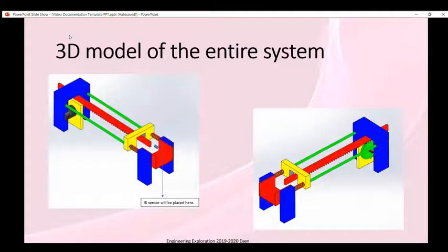Basically, the ball will be placed manually into the holding unit. The IR sensor, which is placed in the holding unit, will sense the ball and give direction to the DC motor such that it rotates for a few seconds. The DC motor makes the rack move forward with the help of the pinion such that the rack applies enough force on the ball and the ball gets launched. So this is basically the rack and pinion mechanism on which the model is working.